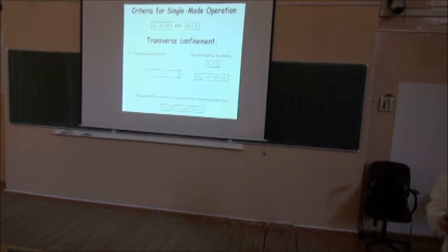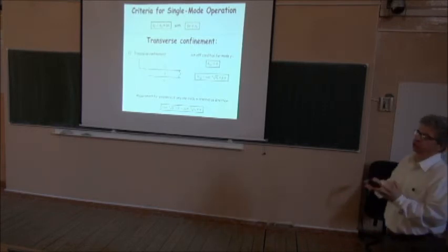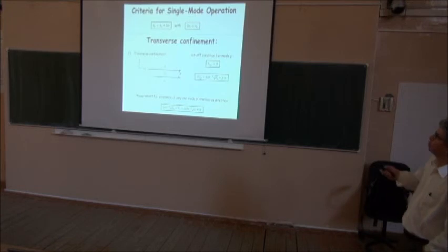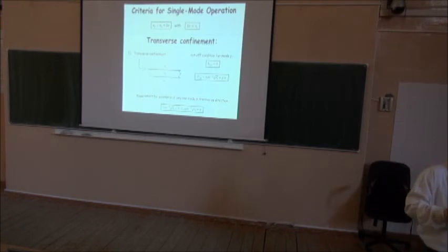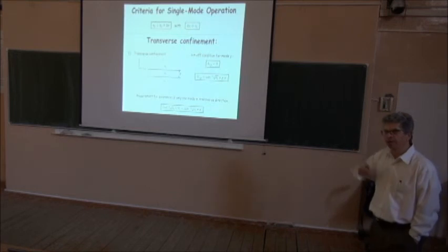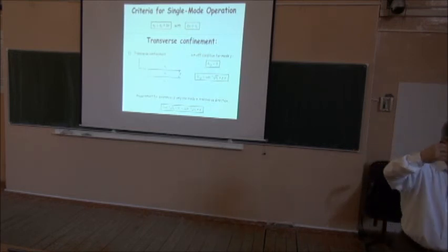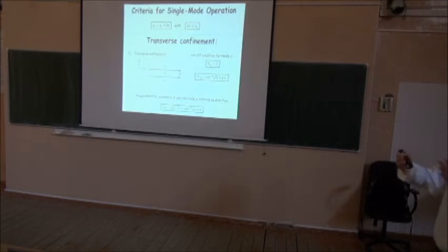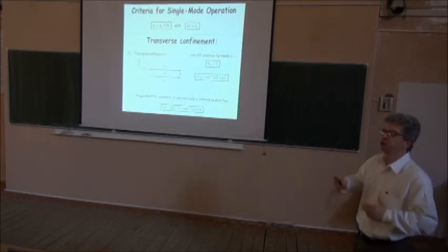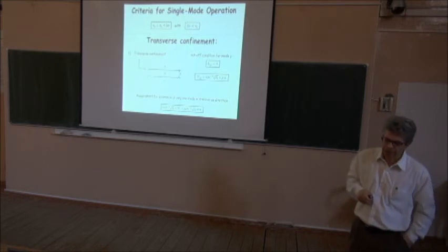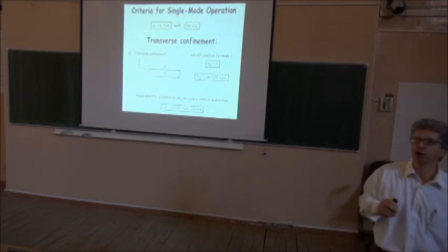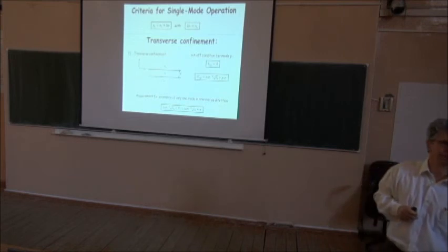But one thing that this last technique is very useful for is to understand and start defining under what circumstances, under what conditions, we will have a single mode operation of a waveguide. And actually that is very important for many applications. As we're going to see tomorrow, in many cases, if you have multiple modes that can propagate, those modes can carry energy with different speeds and they can go out of phase, and that can be problematic in many applications, including your internet signal.